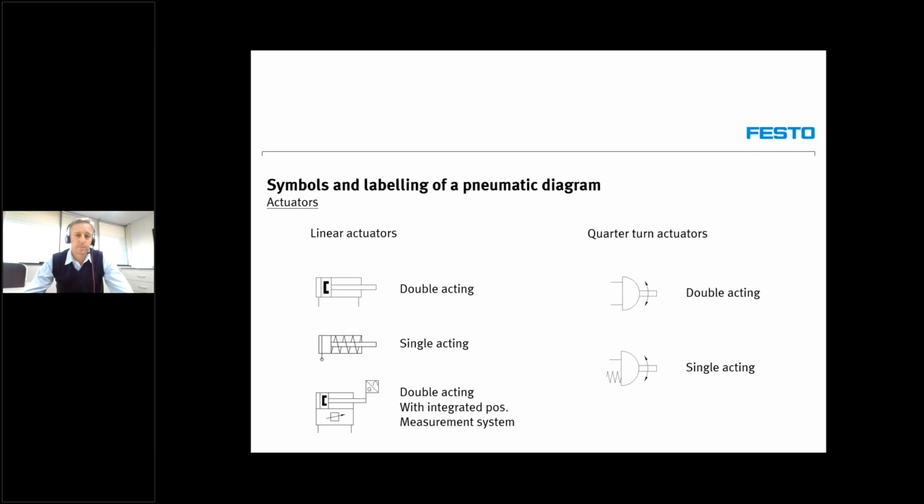Yeah, I think also, once again, in summary, we have a comprehensive tool available to help us select the right type of tubing and fitting and hose for the application. It is application specific, but a small variation in color or material can make a huge difference to the longevity that the particular fitting or tubing provides you. I know that we sell kilometers of tubing for underground applications where there's a lot of exposure to acid.